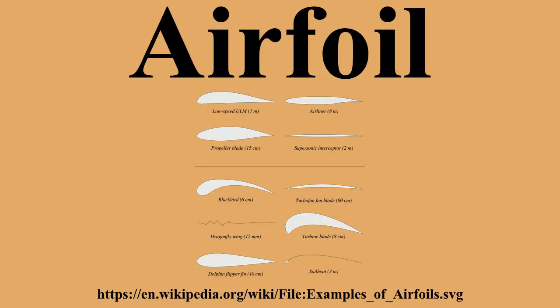Subsonic airfoils have a round leading edge, which is naturally insensitive to the angle of attack. The cross-section is not strictly circular, however. The radius of curvature is increased before the wing achieves maximum thickness to minimize the chance of boundary layer separation. This elongates the wing and moves the point of maximum thickness back from the leading edge.